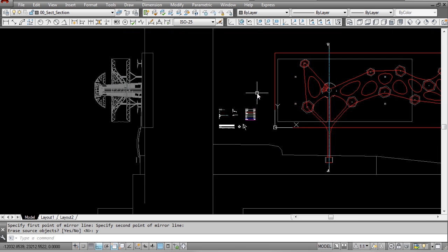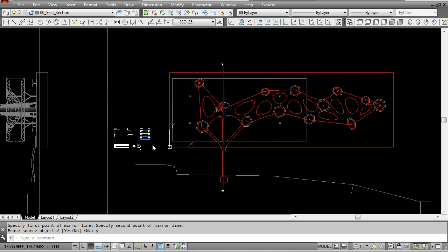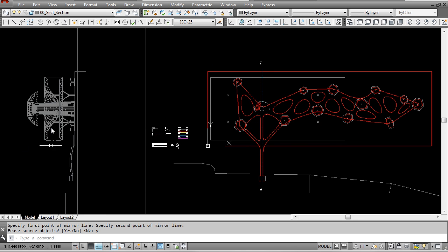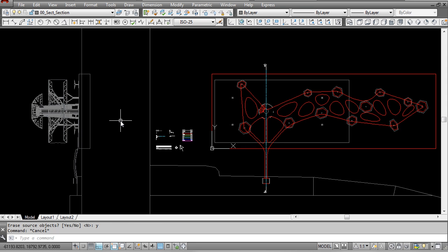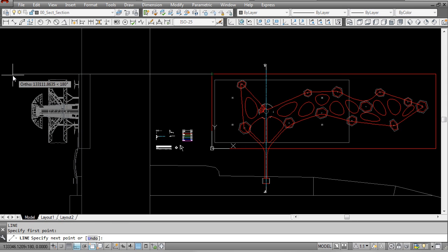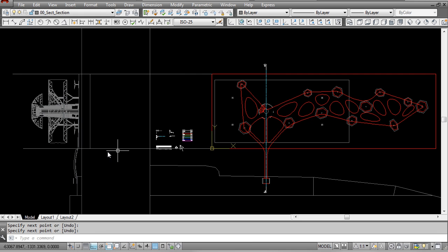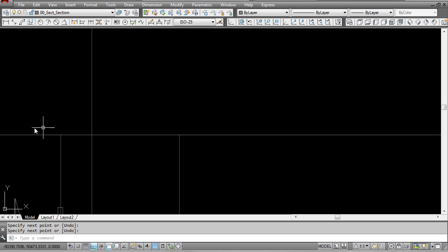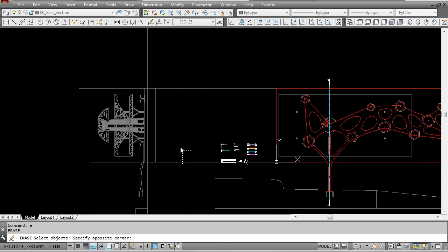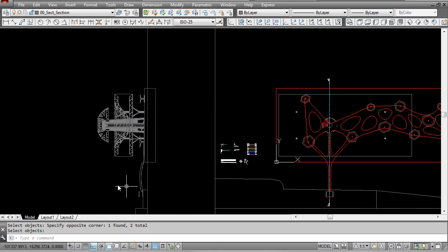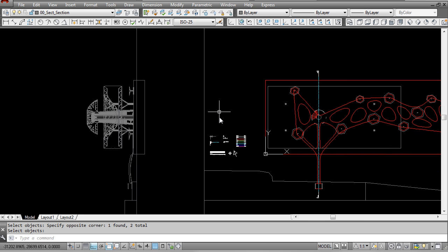So the next thing that I'm going to do right now is to rotate my view so that this is looking horizontal to me. I'm not going to rotate this plan because I do want each of the projected lines to basically be lining up with what I'm drawing. So if I just draw lines extending out of the plinth or the base of this barge, you'll see that it already lines up very neatly and accurately with the edge of our section here. So everything has been kept in place since our 3D model. All we need to do now is actually rotate our view in AutoCAD.